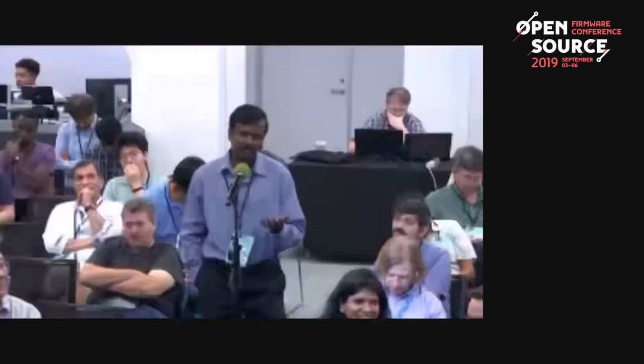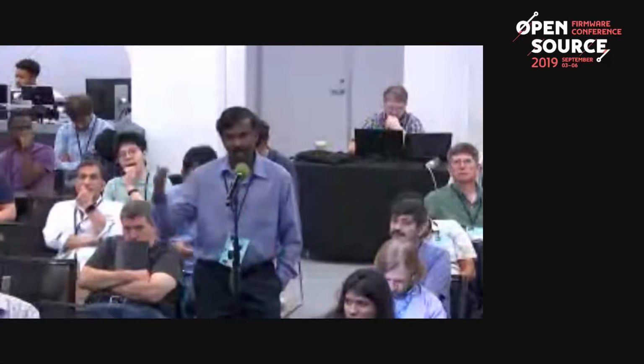But how do you... We strip all that stuff out and it gets better. Don't you need that stuff? ECC init is still occurring, but we strip all that stuff out and it got better. Isn't that supporting my argument? If you take ECC init out, then you crash. No, I'm not saying take ECC init out. I'm saying you demonstrated this really neat thing, a 10-second boot, by stripping out a lot of stuff you don't need. That's our whole argument. I can demonstrate something by taking away things I don't need for boot. But I need it for functionality. If I need BMC logging all the errors that are coming up, I need that functionality. So if you start adding platform functionalities on top of your basic baseline, then you start adding boot time.